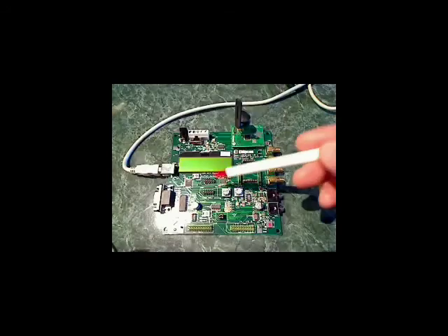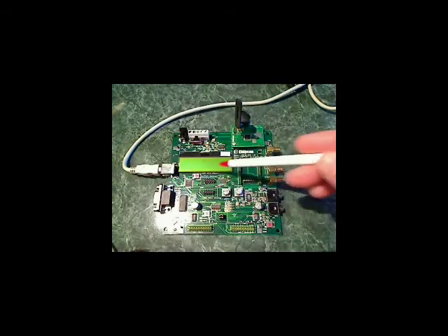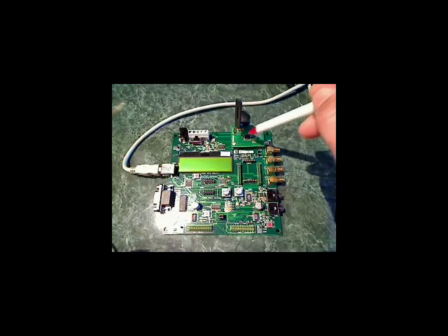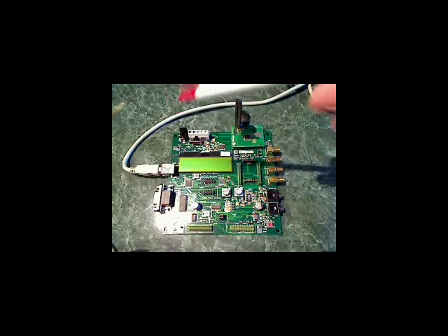Now let's go through the same procedure to take a look at what's actually being transmitted over the air with the TI packet sniffer. I'll be using this SmartRF04 EV board as my sniffer, along with this CC2430 evaluation module that's plugged into it. This 2430 EM board, this radio is an 802.15.4 radio, completely capable of receiving all of the ZigBee packets that are being sent out by the Z-Accel radio.